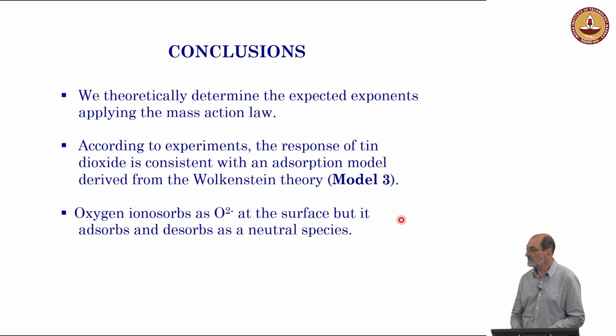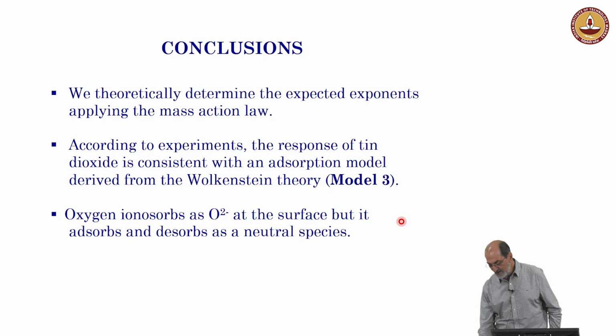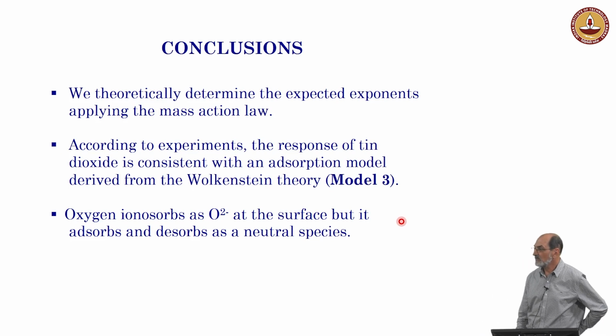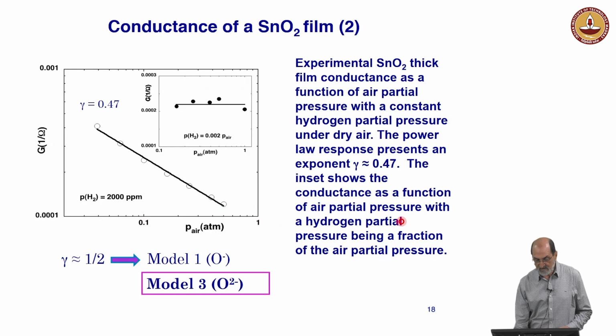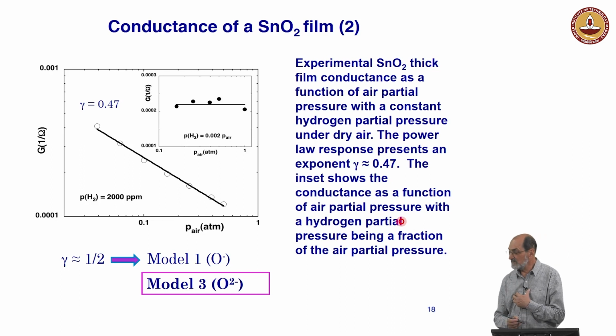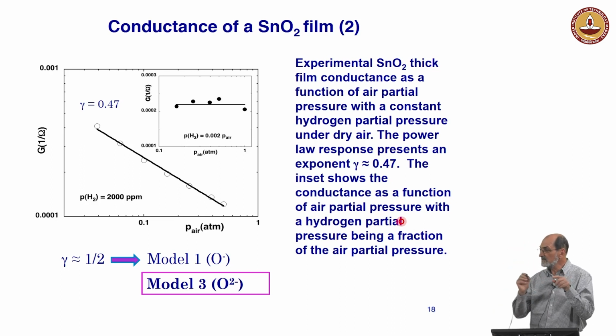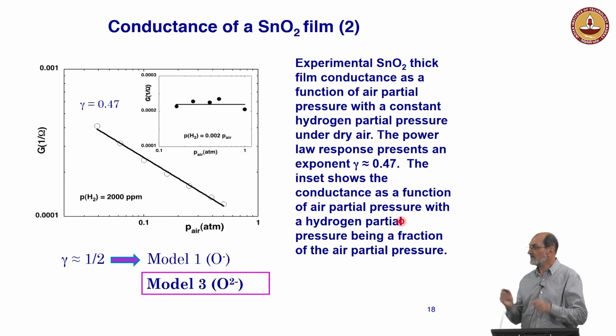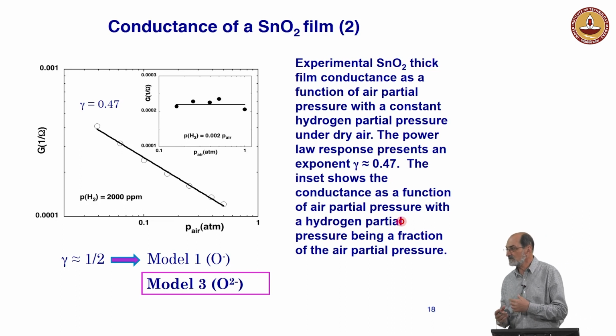Just a couple of questions. So this is all just small grains. Yes. But do you see any grain growth because you're heating this at 300? Yeah, if you heat up more than that, you end up with larger grains. The larger the grains, these relations deteriorate. That is, you start having different slopes, which I think we attribute to band bending, and if you start having band bending, you start having tunneling current, and that depends on the details and the dispersion of the grain size.